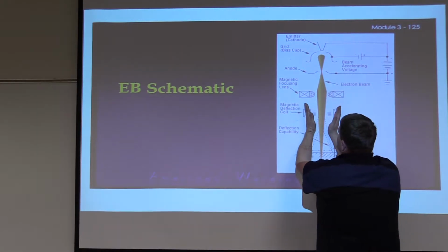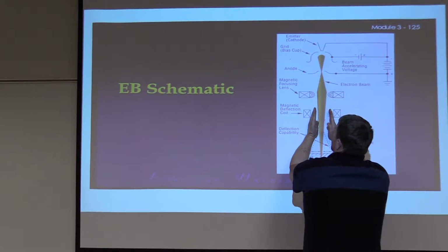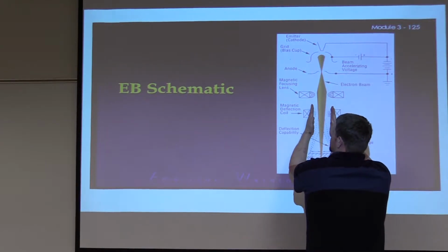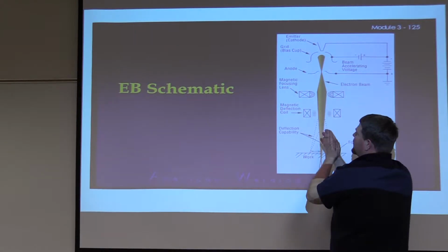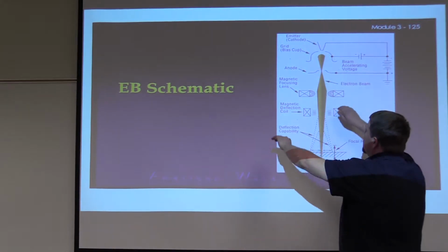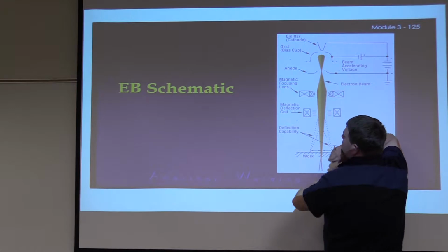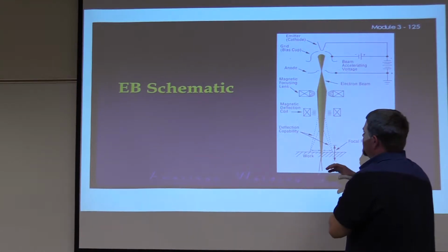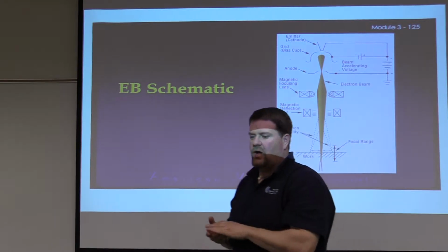You can also tell if your weld material is a straight edge at this point, you're not going to get through the whole entire thing. You have to watch your width to depth ratios at this point, because these are straight walls and this is a tapered wall, right? So it's really important to think in any welding process, what can this do for us? Now you can pull these focusing lenses out a little bit and let that spread out some to get a little bit more of a width, but you may not get as much intensity as far as heat there either, okay?